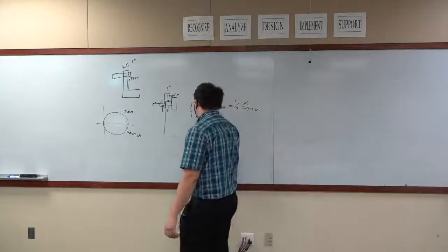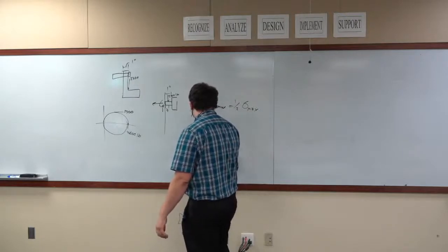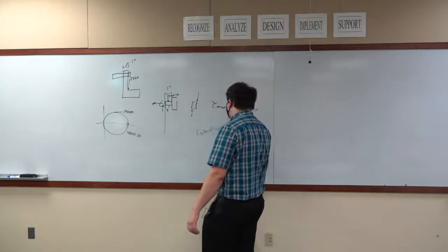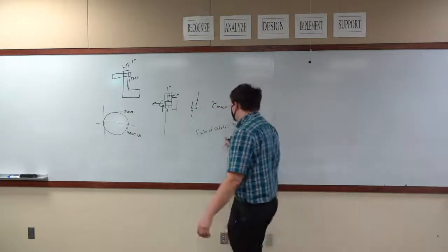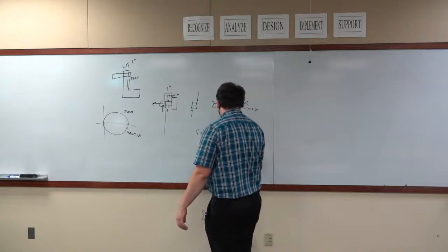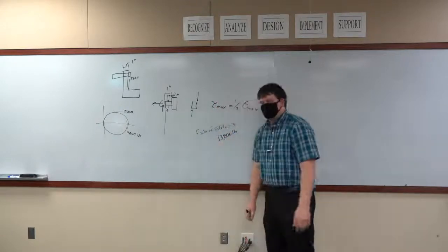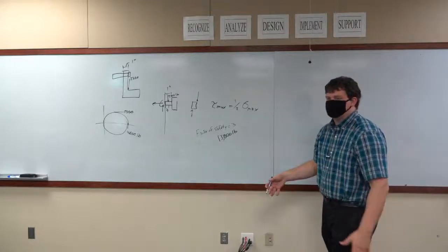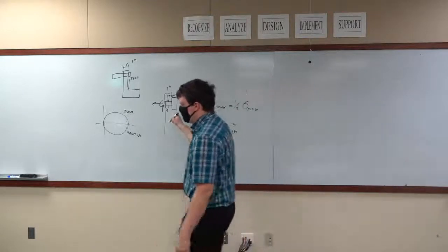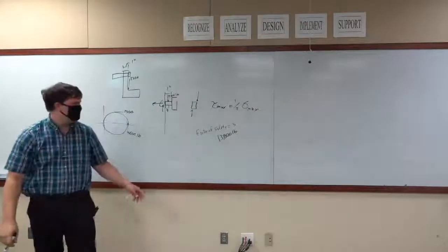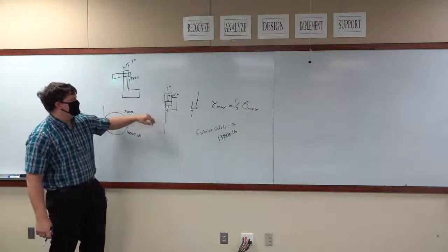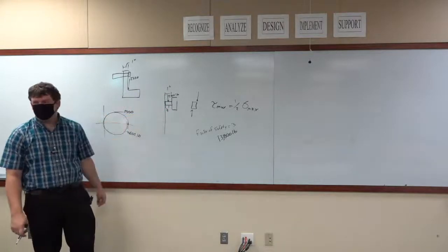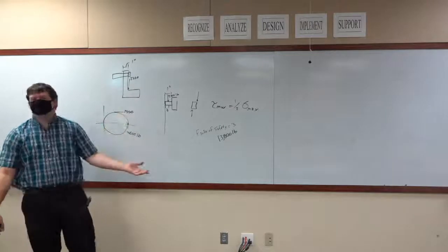Maybe I say, let's go with a factor of safety of 3. So now I'm looking for a bolt that has 13,800 pounds. Okay, if I find a bolt like that, I'm good. Doesn't matter the material, doesn't matter the size, doesn't matter the threading. Now as far as the length is the other one that I'd have to pick. Again, I said I like to take a bolt and the amount that it sticks out is the amount that it sticks in. I'd probably want to make this be 2 inches long.